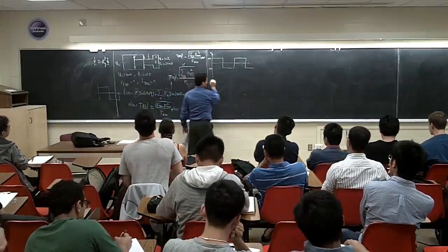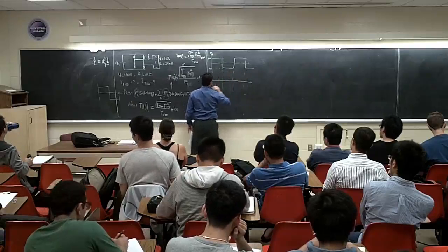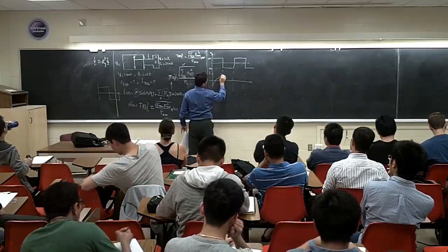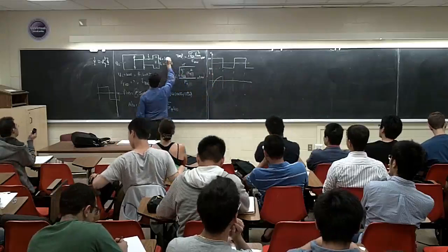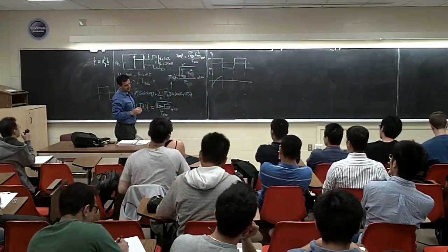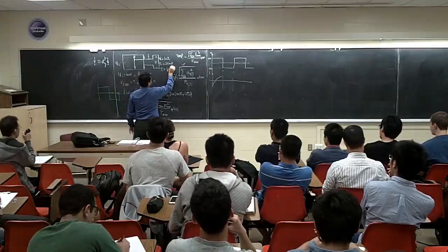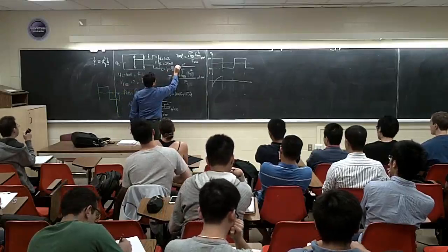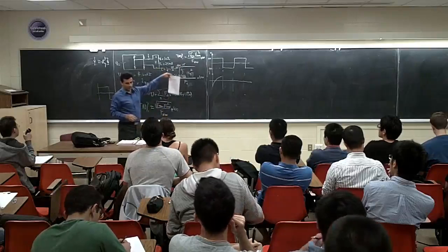How about the current waveform? I'm plotting during the steady state, right? So basically, if this is the current, this one is based on, this is 60 hertz, most probably. Let's say how much is the time constant for this one? How much is the time constant here? Tau is how much? Is L over R, am I right? L over R. So it's going to be 25 divided by 10, which is 2.5 millisecond.